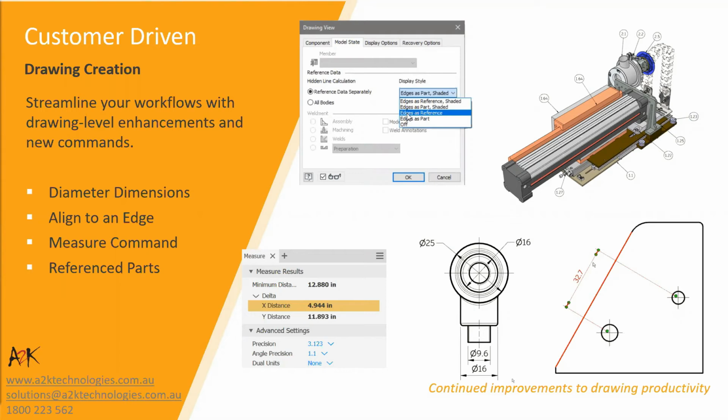You can now align a dimension to a selected edge. Use the new dimension type, rotated, to place a dimension and position on a perpendicular edge so that it aligns to the selected edge. The measure command is now available in drawing files. This was also brought into 2020.3 Inventor, just in case you were wondering.